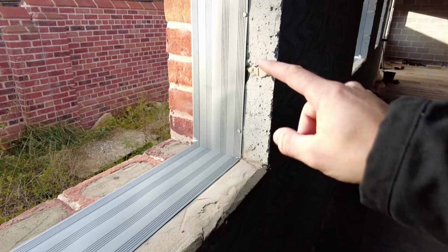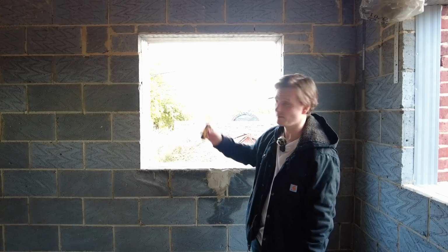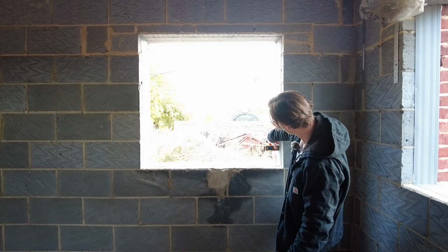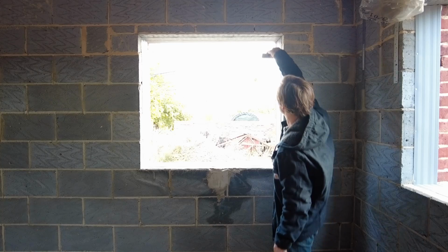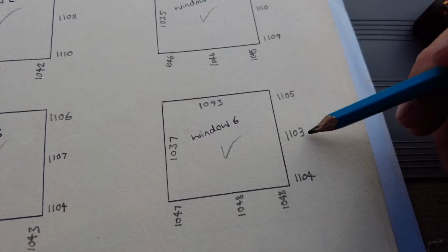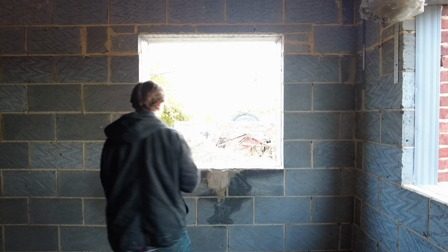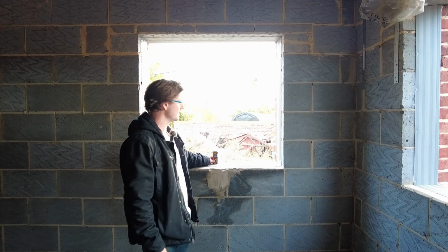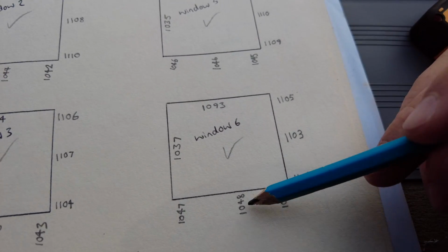First things first, you definitely want to make sure you put your cavity closers in before you measure up. With a laser measurer or your measuring tape, you're going to take 3 measurements horizontal. One about here, one in the middle, and then one at the top. You take them measurements, write them all down. From there, you're going to take 3 other measurements, one on the side, one in the center, and one on the edge. You write down them 3 measurements as well.